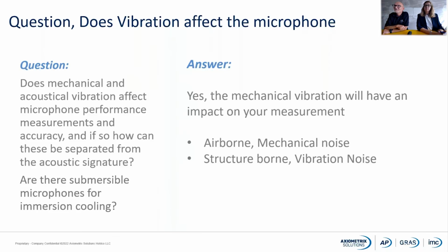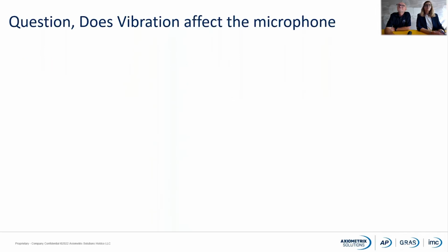So you're actually measuring the noise from this object vibrating a lot. If it's structure-borne, then maybe your microphone has been mounted on a part which is generating a lot of noise. So this noise will actually vibrate the microphone as well.